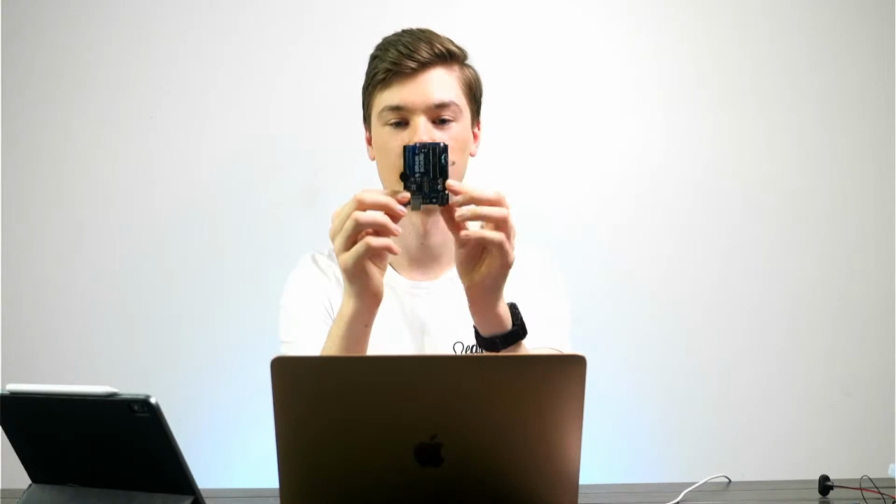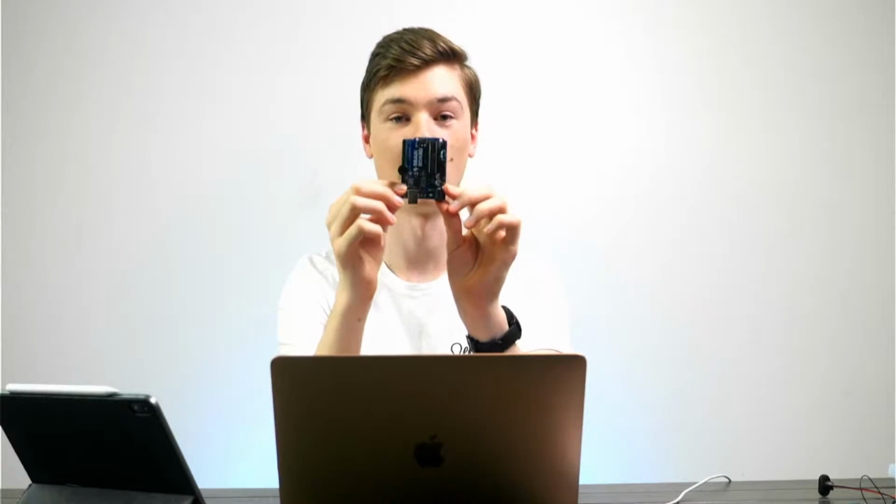Now we have a question from Mediha. I hope that's the correct pronunciation. In the Arduino software, the port button isn't working for me. What do I do? So I went over this before, but it's really important that you check if your Arduino board has lights on it, because if your Arduino board isn't connected to the computer, you can't upload code to it. Over here on the brain board, my board has no lights on it, which means there's no power to it.